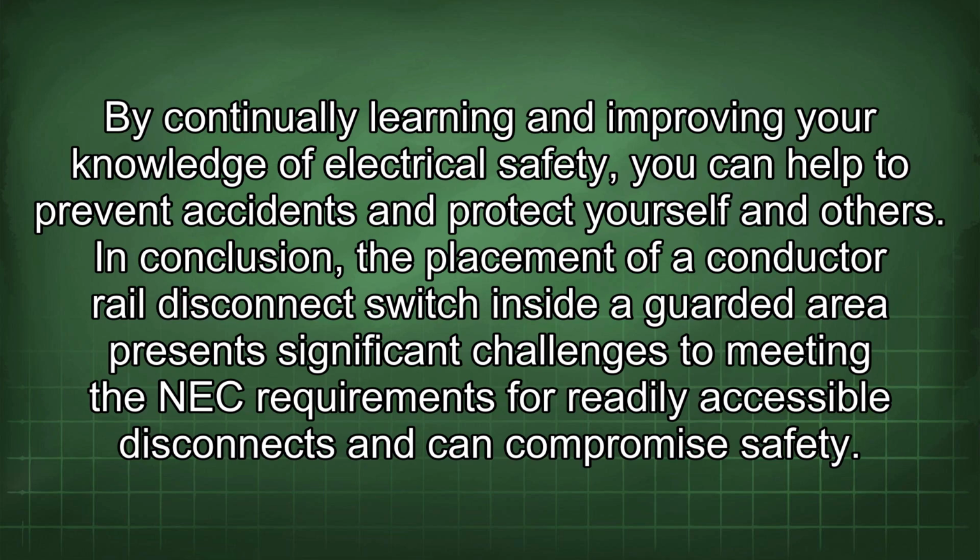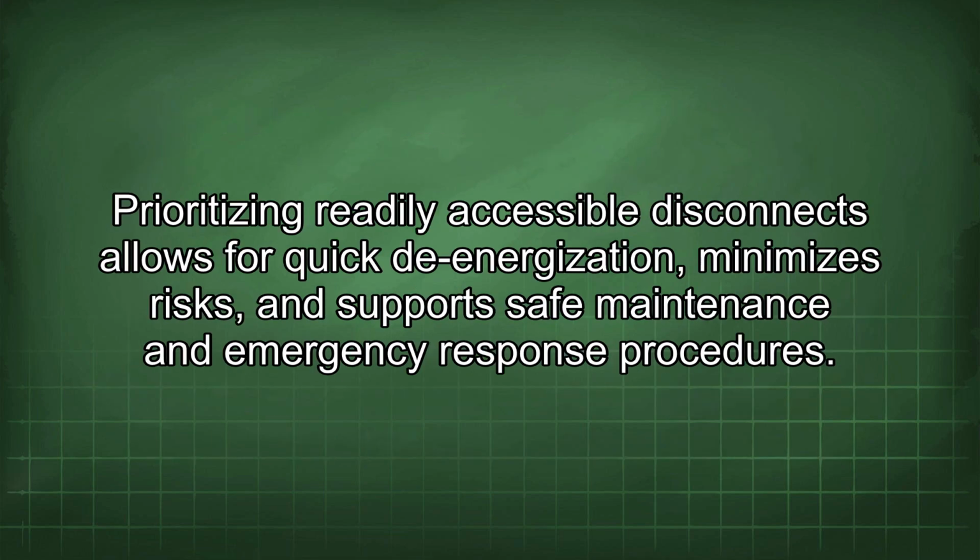By continually learning and improving your knowledge of electrical safety, you can help to prevent accidents and protect yourself and others. In conclusion, the placement of a conductor rail disconnect switch inside a guarded area presents significant challenges to meeting the NEC requirements for readily accessible disconnects and can compromise safety. Prioritizing readily accessible disconnects allows for quick de-energization, minimizes risks, and supports safe maintenance and emergency response procedures.